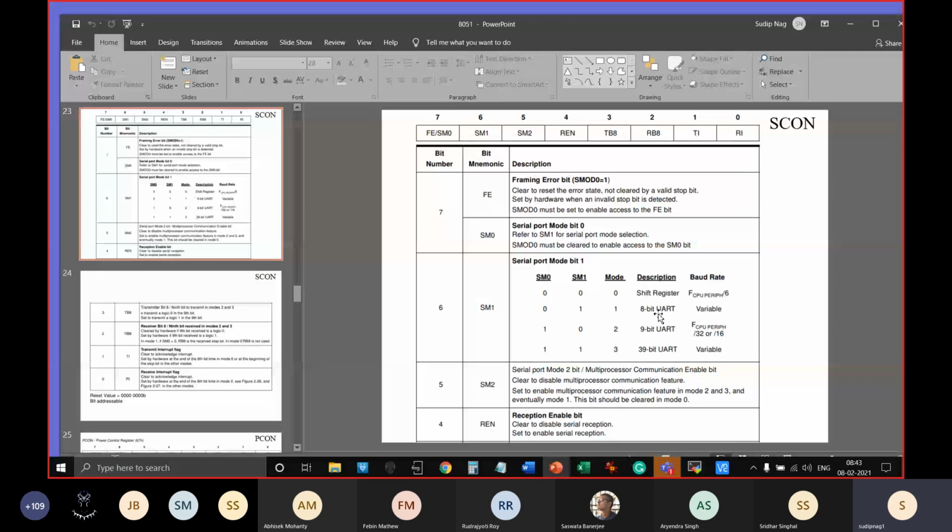Every time you send 8-bit data, 2 more bits come as a penalty or overhead. So let's reduce the overhead and use a longer data frame, a 9-bit data frame. But again, it is error prone, because less synchronization happens in the absence of start and stop bits. So this is almost not used.